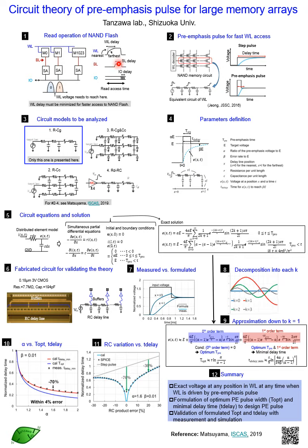Bit line sensing operation cannot start before all the gate voltages reach the target voltage, because the sensing operation is done simultaneously, and therefore the read access time is composed of word line delay time, bit line delay time, and I/O delay time.